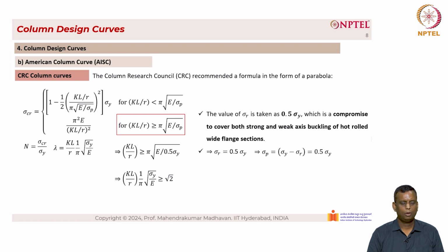We also know that n equal to sigma critical by sigma Y and lambda equal to KL by r into 1 by pi into root of sigma y by E.